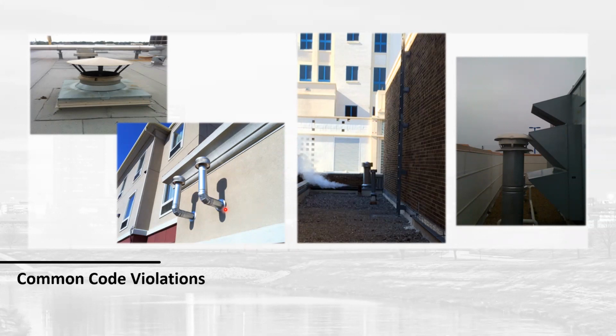So we informed the contractor of that. So they decided to put a 90 and a piece of pipe with a cap. That still doesn't qualify because you have to exceed that parapet roof by 3 feet, but then you've exceeded the amount of exterior B-vent, et cetera, et cetera. So a lot of issues there. We could fix that with a couple of cap fans right on the sidewall there.